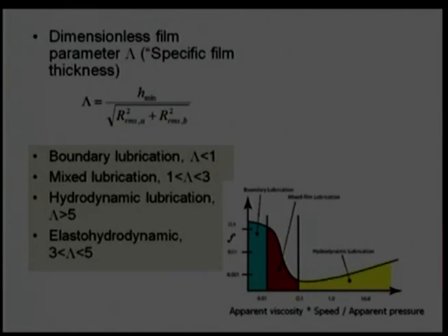The coefficient of friction is going to decrease. It reaches the bottom, the minimum value, and after that it again increases. So, if we want to design a tribo pair, a machine component, we should prefer this lower portion where the coefficient of friction is a minimum. That should be our target, and if it is not achievable, then we may negotiate with hydrodynamic lubrication or, to some extent, a mixed lubrication mechanism, depending on the operating condition and on the device for which we are working.